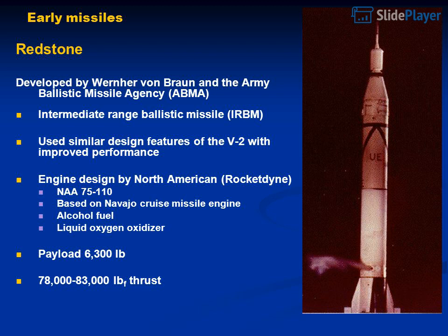Early missiles: Redstone. Developed by Wernher von Braun and the Army Ballistic Missile Agency, ABMA. Intermediate Range Ballistic Missile, IRBM. Used similar design features of the V-2 with improved performance. Engine design by North American, Rocketdyne. NA 75-110, based on the Navajo cruise missile engine. Alcohol fuel, liquid oxygen oxidizer.